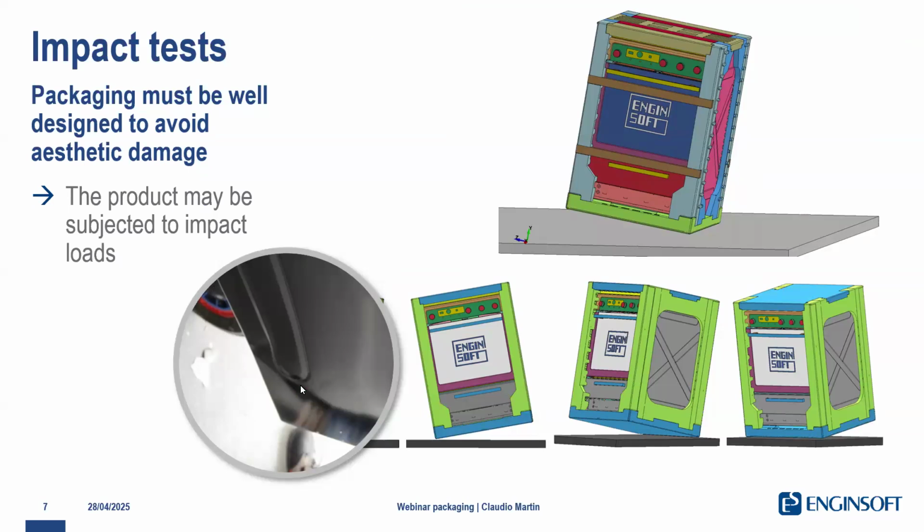During loading and unloading, the product may also be subjected to falls or slips, which are described in the transport regulation as impact tests. These are free fall from a certain height or slip on an inclined plane that cause the product to hit a hard surface. At the end of this test, the product must not show any aesthetic or functional damage. And as before, simulation can help to select the best packaging configuration by choosing from different geometries and material densities.